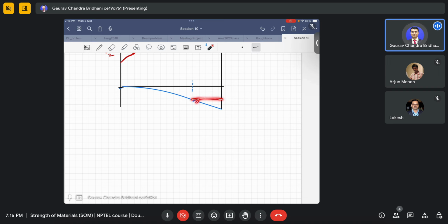So we use that slope, and we need to find this much value, because this much deflection is already at this point. We know this much deflection, which is the same as this here. So we know this deflection here, we need to only find this much deflection. What is this? To find that, we say that this is very small, because as the professor has told, this means a small deformation, we always have theta less than 4.7 degrees, or less than 5 degrees.